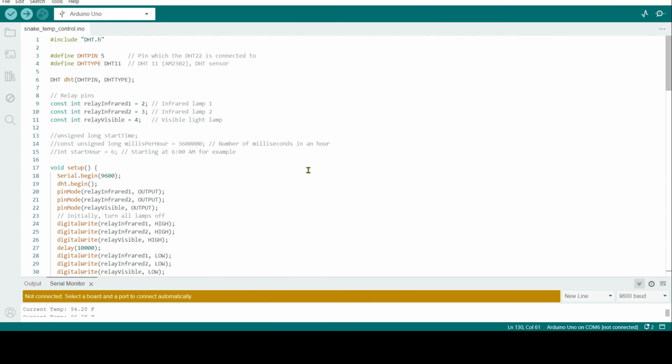And I would also like to add redundancy in the relays. The relays that I got are just cheap relays from Amazon, and they work well, but they do sometimes get stuck. That's why I had to add the delay in there as we're sequentially turning on more and more relays. It could be a power distribution issue. There's a lot of things it could be.